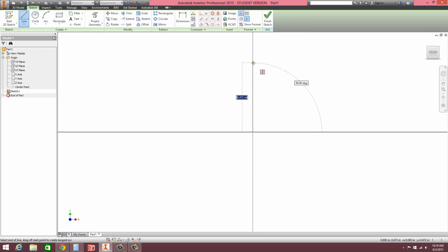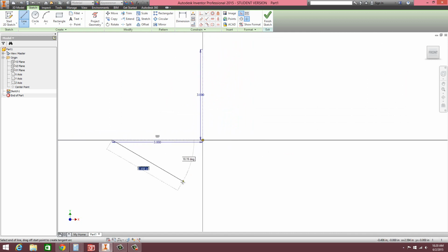Right at the origin, click and drag up a vertical construction line. And as I'm dragging up here, we'll put in a value of at least 3 inches. And from there, just go ahead and hit escape. Let's go back to the line. Construction is still selected for us, so we could draw a horizontal one. So drag it across. And this one, we'll make a good 3 inches as well. Then hit escape.